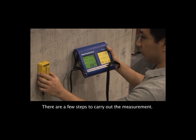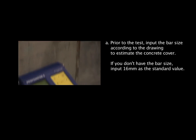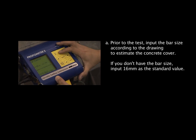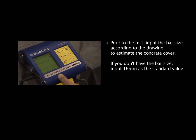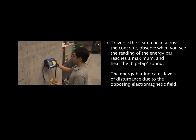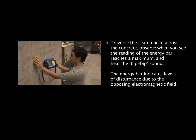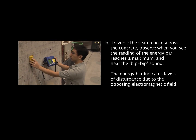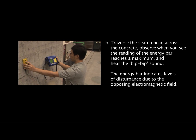There are a few steps to carry out the measurement. A. Prior to the test, input the bar size according to the drawing to estimate the concrete cover. If you don't have the bar size, input 16 mm as the standard value. B. Traverse the search head across the concrete. Observe when you see the reading of the energy bar reaches a maximum, and hear the beep beep sound. The energy bar indicates levels of disturbance due to the opposing electromagnetic field.